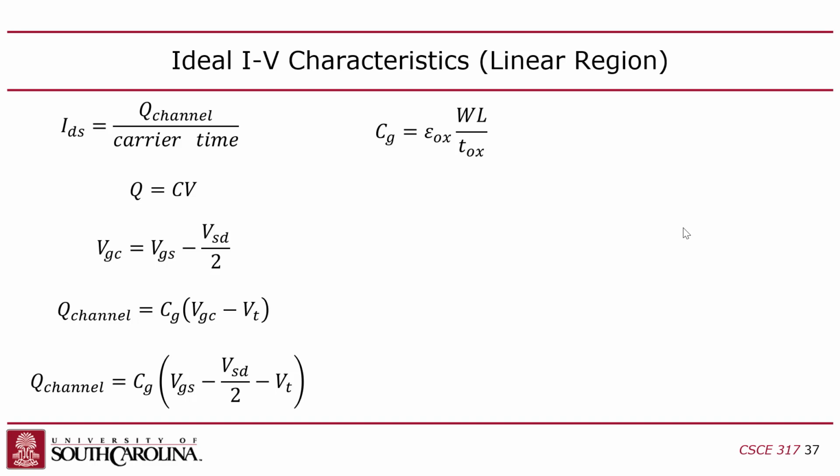And then you multiply that by the area of the capacitor, which is width times length, and then that's divided by the thickness of the oxide, how close you get the two plates of the capacitor together, right? And so yeah, that's 3.9 times epsilon 0, that's the dielectric constant of a vacuum.